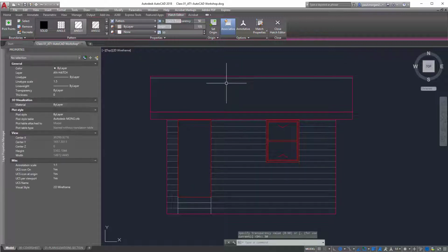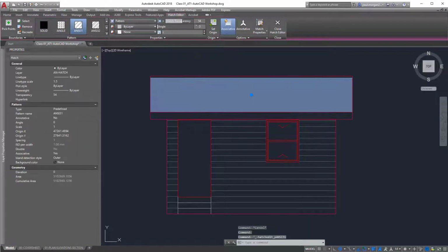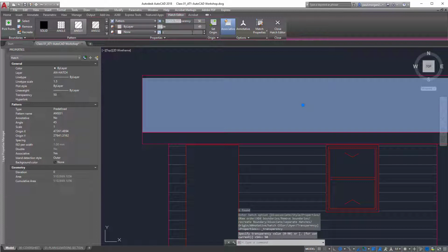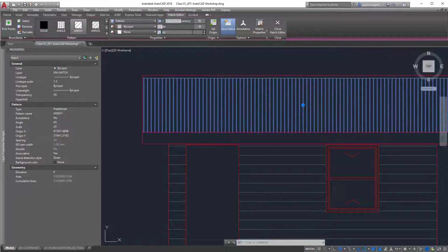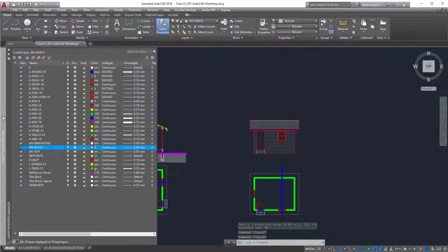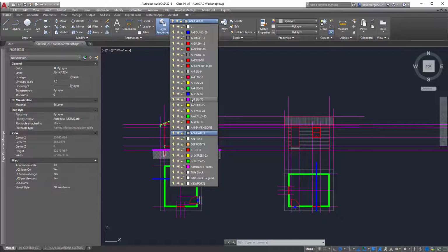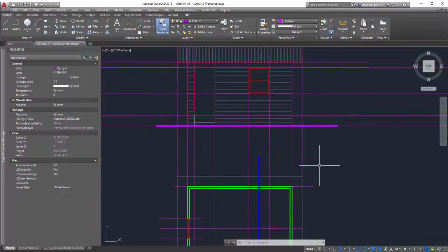That looks about right. And then again, hatch for the roof, click. I'll use that same hatch again. This time I will rotate it 45 degrees, so that way it's directly up and down for our tin roof. Make sure it's got a transparency of around 50 and a scale probably of around 20. Looks good. Okay, so that's one elevation. And then finally, you've got the thick ground line, which is a pen 70, which I'll just run from one side, randomly from one side of the building to the other, generically.